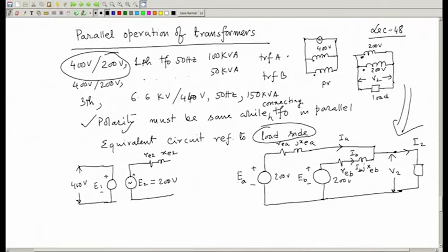Instead of doing that, purchase another transformer of lower kVA, but having the same voltage ratings, and connect them in parallel, so that the old one is not removed from the circuit. In this way, as demand increases, you can connect two or more transformers in parallel and supply the new load demand. Each one will contribute to the load.